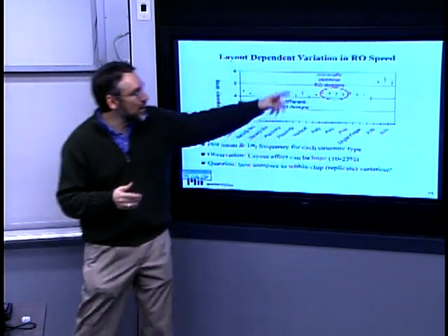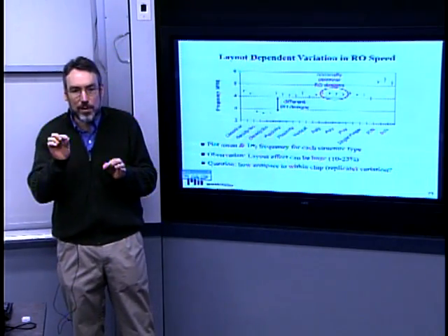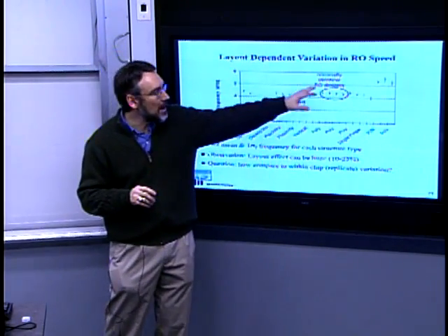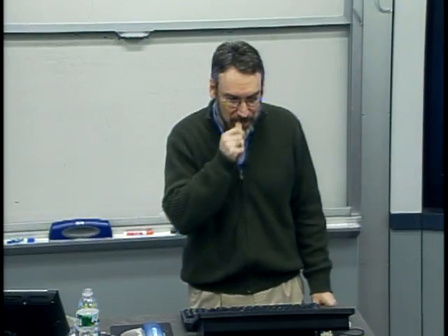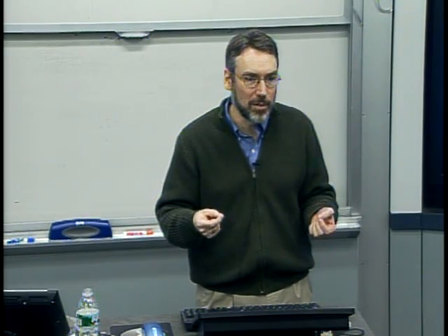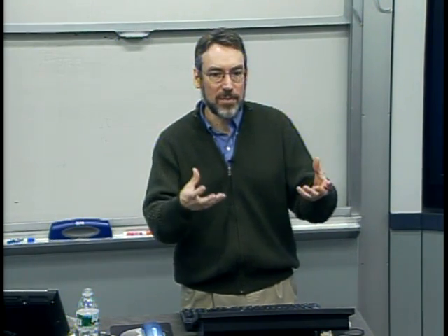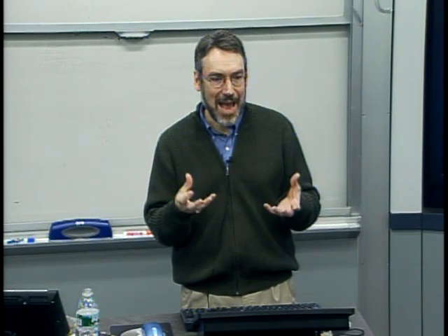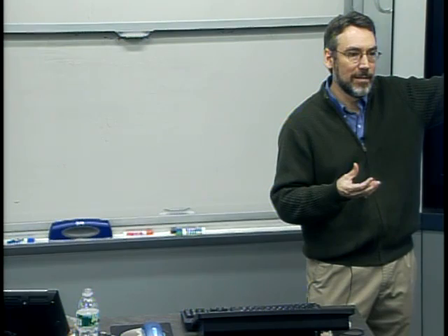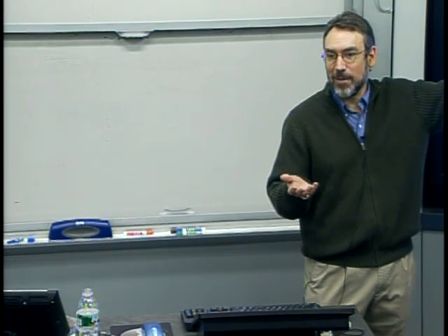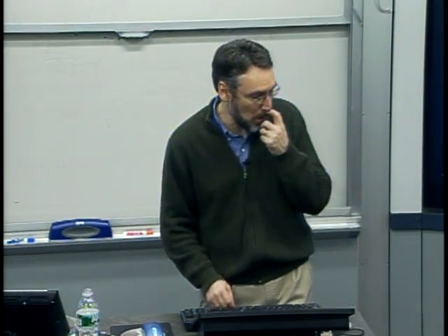But in fabrication, because of neighborhood or nearby structures, in fact, there are slight deviations. So nominally identical transistors may in fact have substantial, systematic, highly repeatable effects. And if the manufacturing line can capture and characterize those and send that information to design, design can compensate, right? So this is another theme. This design and manufacturing link can be very important.